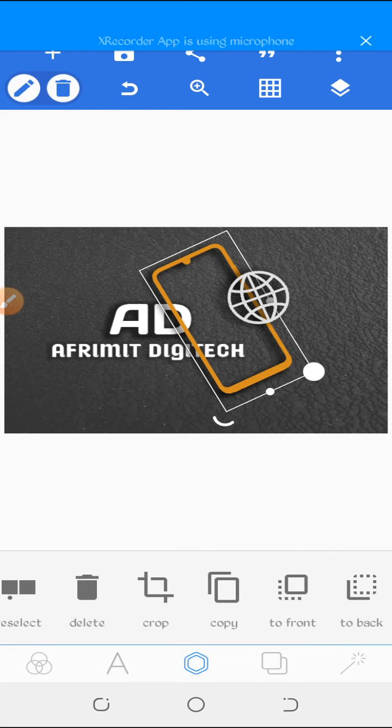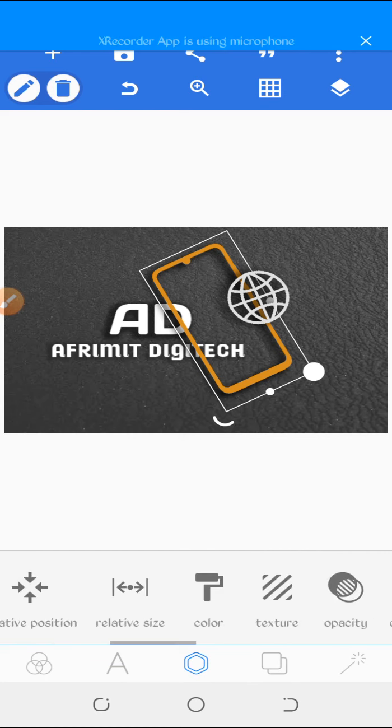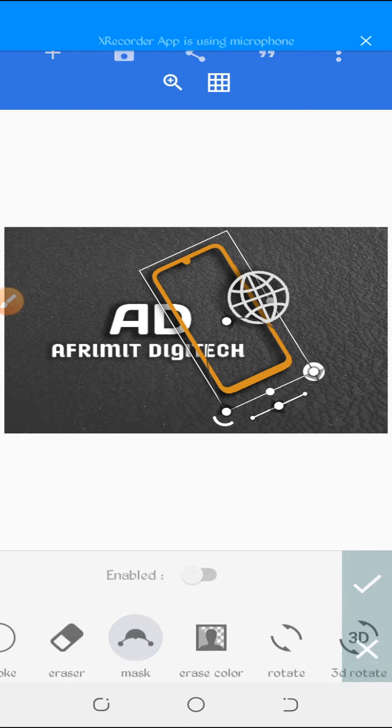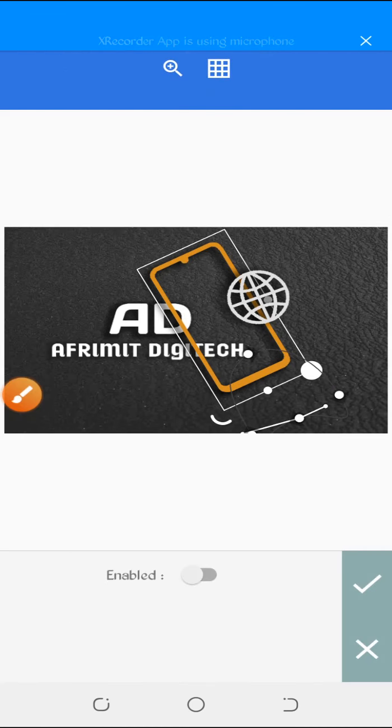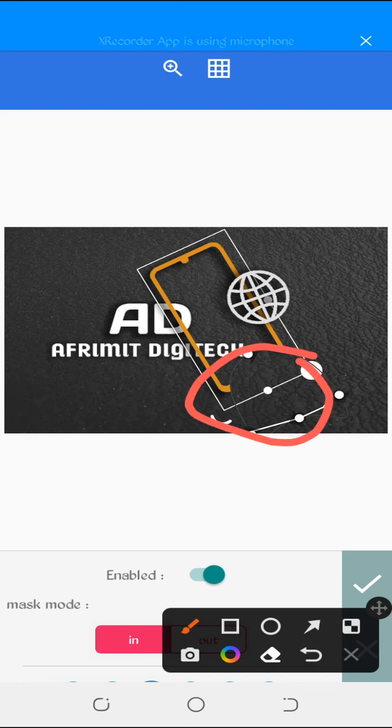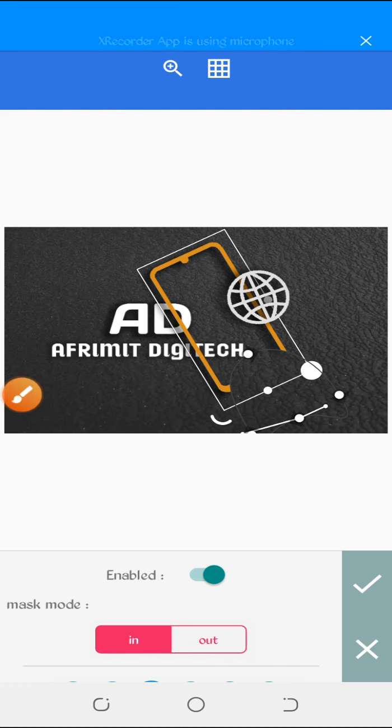Just still on this section for the objects, then I will use the tool that is called mask tool. So when you click on the mask tool, you should be seeing something like this. The first thing you need to do is to click on this enable here so that it can be enabled. If you click on enable, you see it has erased part of this here. See, it has removed this place, but that is not where you want it. So the next thing is to move it around.